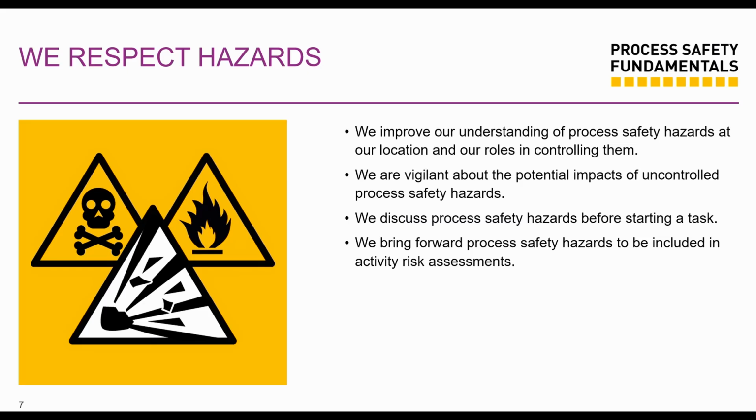Phosgene, they're just a long list of them. And you want to be able to respect those hazards because, hey, you're adding pressure, you're adding lots of heat to them, you're taking them to temperatures over 100 Celsius, 200 Celsius. You are keeping them in pressures over 10 bar, 1,000, so 1,000 kPa. So you want to make sure that you respect that process.